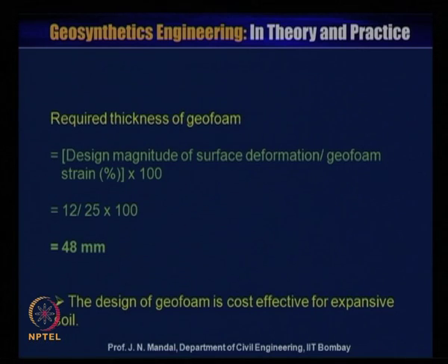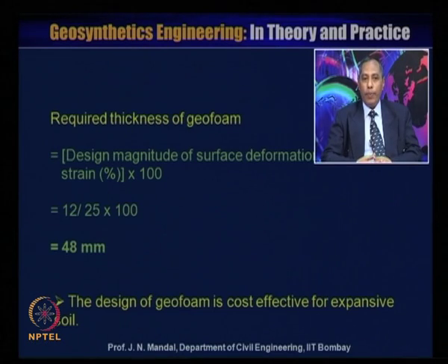So the required thickness of the geofoam is the design magnitude of surface deformation divided by the geofoam strain in percentage, into 100.